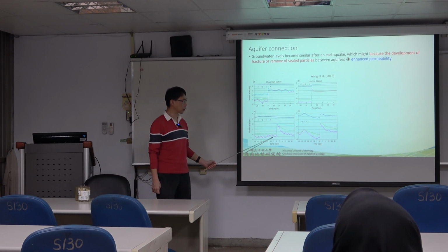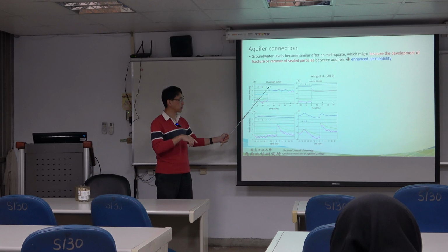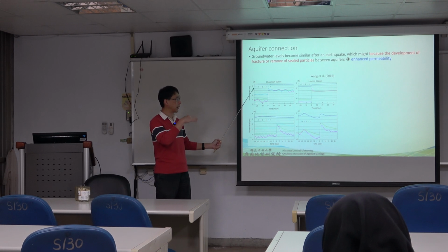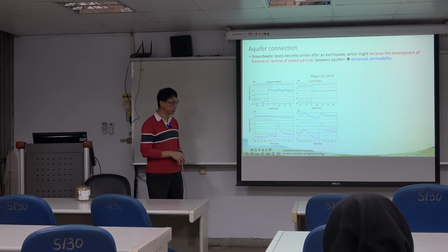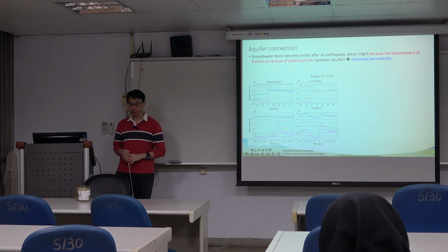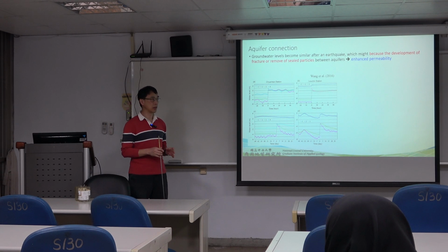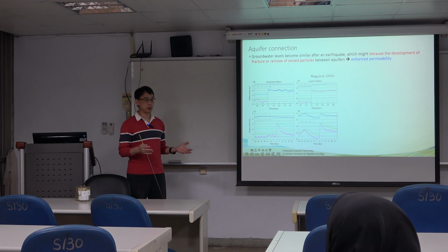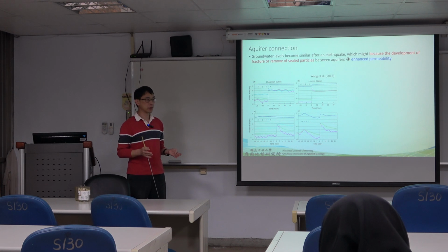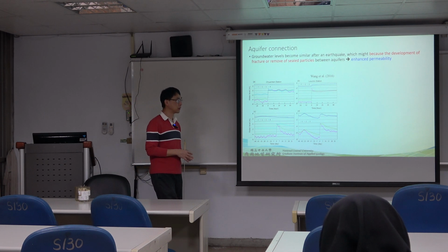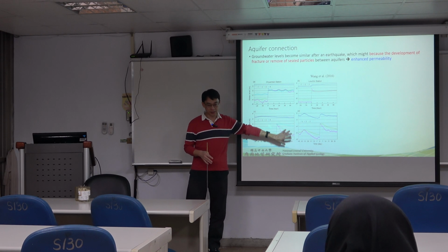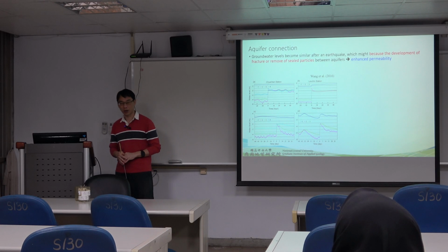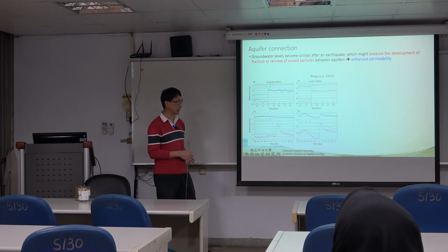So we might be able to see that the ground levels become the same or consistent, like these kinds of patterns. Originally, before the earthquake, they are separated. But after earthquake events, some of the wells seem to be connected, and they call that permeability enhancement. We can also say that it's a kind of damage process. When the aquifer system has damage, there might be connections because there might not be a significant aquifer to seal the system. But another difficulty is that there could be device problems or setting problems. It's not exactly aquifer damage.